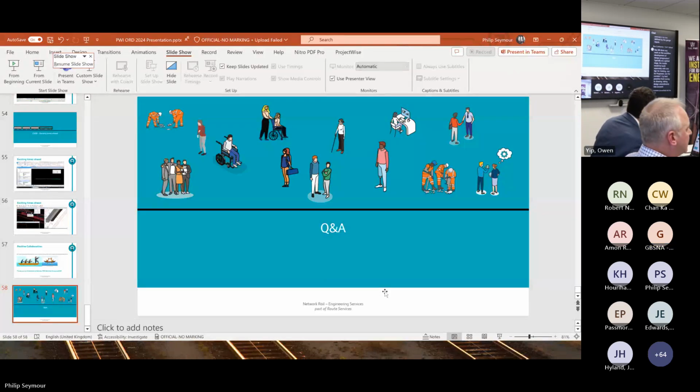Sorry, can you hear me okay? Can I just clarify that one? Hi, it's Alex. It's more the position, not the size and the zooming. I understand how to amend the size, but it's the position of it on the center line that needs offsetting to sort of the CES or 6 foot so that you can actually read it, because it's obscured by the rails. When you've got the topo or multiple lines together, you can't see it easily, even with an increased scale. So I was just wondering if you could offset it like you could in BRT. You could have it offset to the track corridor. I was wondering if that's within the feature definitions.